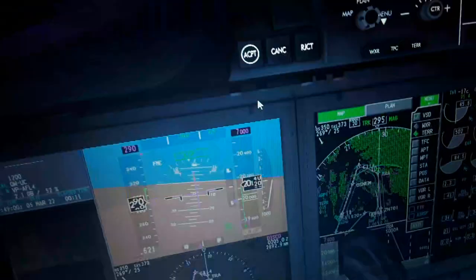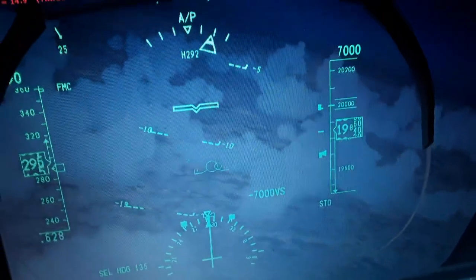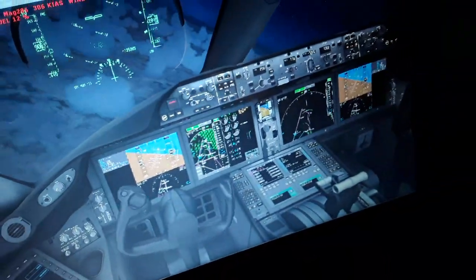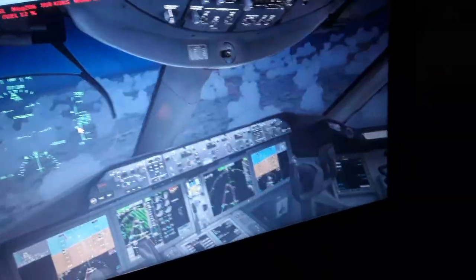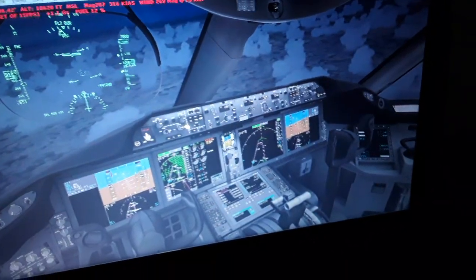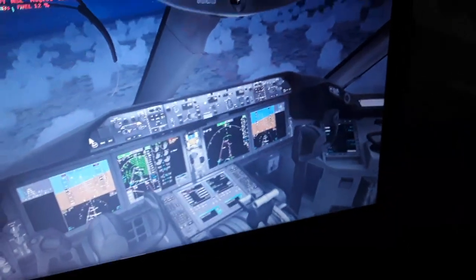Like this, you can see the autopilot now is engaged. We have the AP on here in the display. So we keep flying. Also descent rate increase. We need to follow the waypoints. We take back manual control whenever needed.